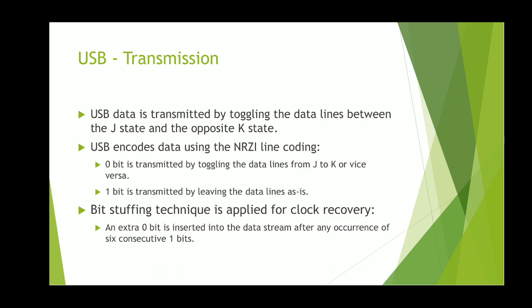And if such a thing happens, the clock recovery circuit in the peripheral devices cannot recreate the clock from the data. So in order to prevent that issue, we use a bit stuffing technique. In the bit stuffing technique, we add an extra 0 bit after 6 consecutive 1 bits.